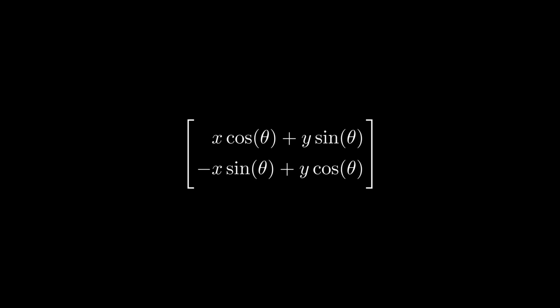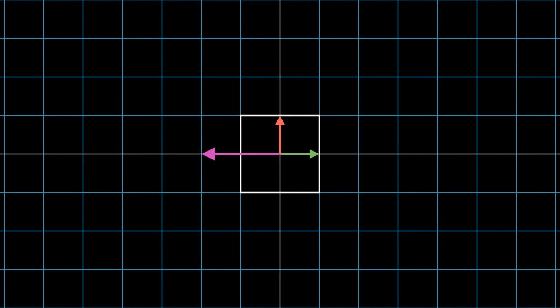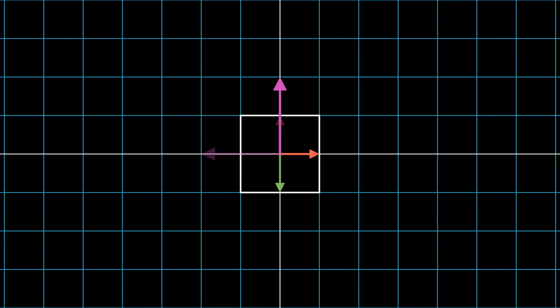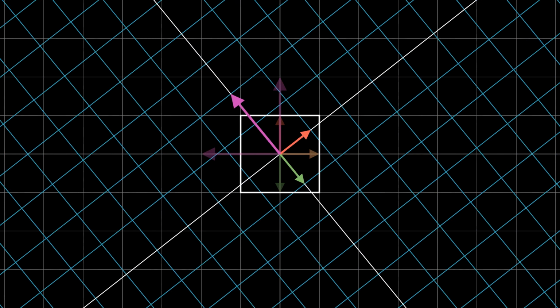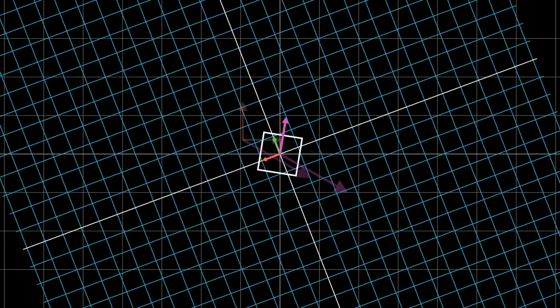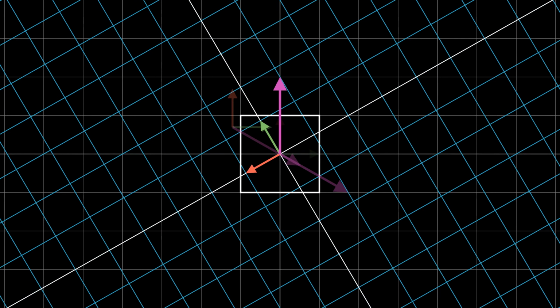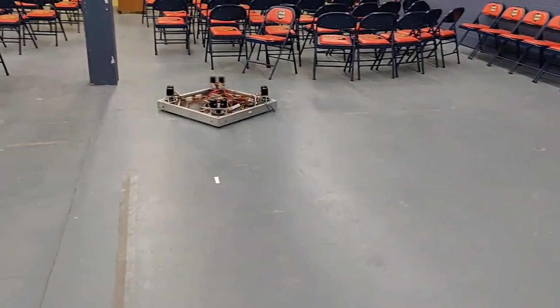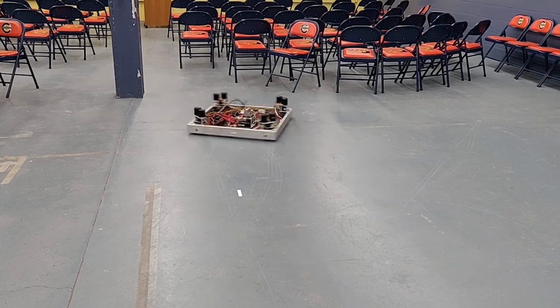Intuitively, this new vector doesn't seem very useful, but now, let's show it in a linear transformation. Since our robot was offset by 90 degrees counterclockwise, we're going to be taking our vector and rotating it 90 degrees clockwise to compensate. The result of this operation is a modified command that we feed into our vehicle. If we use our robot's orientation, you'll see that we're tricking the robot to move to its right, which would be our forwards. You can repeat this for any orientation on the robot, since the rotation matrix will always change based on the robot's IMU reading. The result of these operations done over a continuous period of time is smooth driving that is intuitive and adaptive for the robot operators.